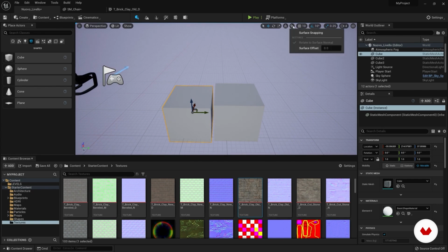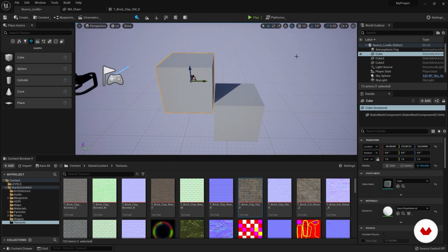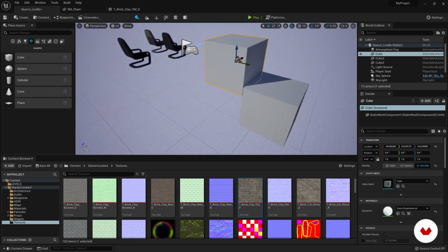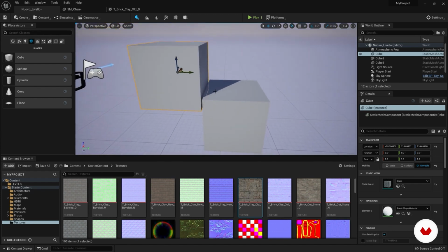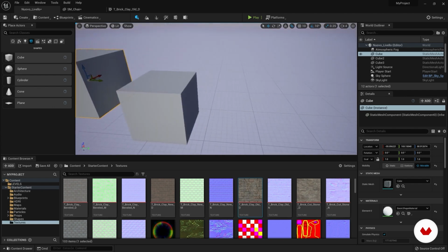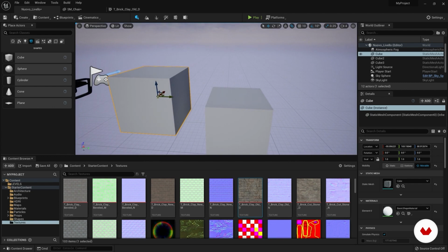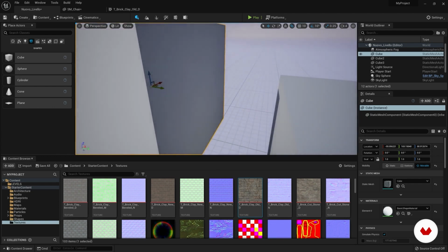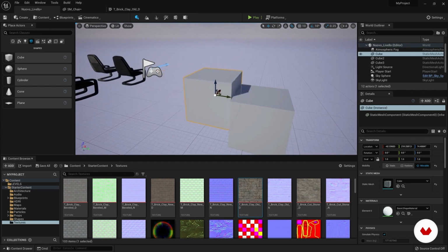A very important snap is the surface snap, which allows us to snap to surfaces. Surfaces snap between the center of the object and the surface of the neighboring object. You can see by experimenting that it actually doesn't seem to work. It does not snap to any surface. The only way to do this is to move the object, dragging it from that ball that you see inside the gizmo. Then I drag. Now the object will automatically position itself on the surface of the neighboring object.